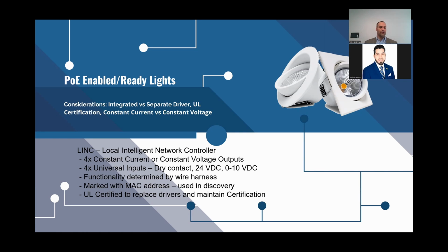What that means as you speak to the manufacturer is that you ask them either to send it without the AC to DC driver, or you just buy it off the shelf with the expectation that you're going to disconnect the wires from their supplied LED driver and connect them to your intelligent node.